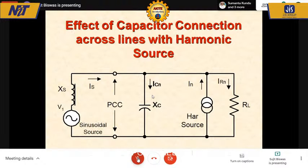So if I go into the details of this network, into the nth harmonic, you'll see that all the nth harmonic will start flowing through the capacitor right here itself, because this reactance will be n times larger for the nth harmonic. So you thought that your power factor can be taken care of by connecting a capacitor, but you find that for some unknown reasons, your power factor correction capacitor is carrying a much, much larger current, because all the harmonic currents will start sinking into this.